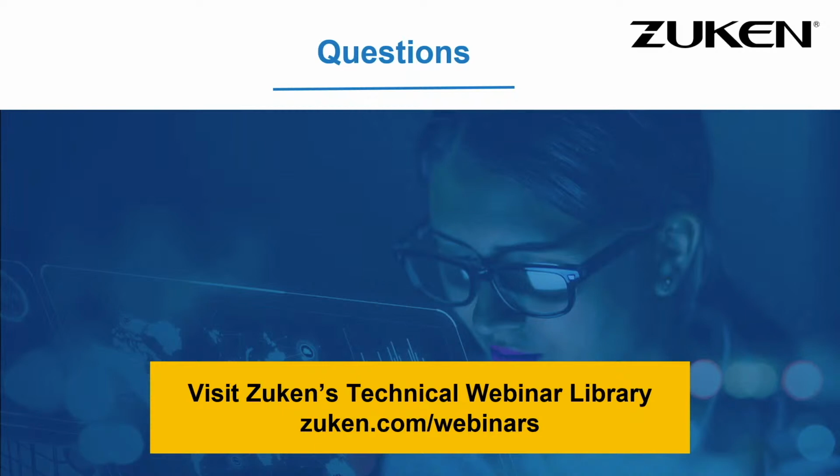When you have that schematic information, as we all know, E3 series is a multi-view tool. The form board is another view of that schematic. So all that component device information is going to match what you have in your schematic. And essentially what the E3 3D transformer is bringing over is all the length information and flattening that data. I hope that answers your question. Essentially the process is just the functionality of E3 series. It's putting another view of what you have in your schematics already, and all that information is linked.